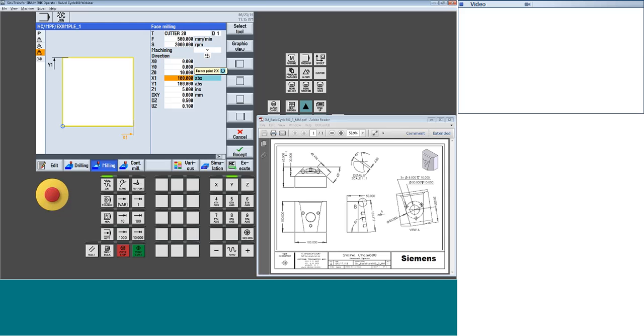Then from there, you define the overall, just like you would in a normal facing cycle, so 100 mil. Now, my Y isn't really 100, because 100 would have been relative to the top. But I'm coming down this plane, so I see that the overall dimension of that is 101.1. I could tell this 102 just to make sure I clean everything up. My absolute end position was going to be a 0. My step over is going to be 65% of my cutter, let's say. And my depth per cut, we'll do like 5 mil and no material for a finished cut.